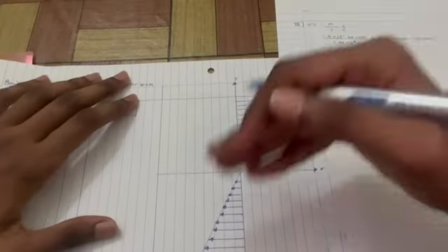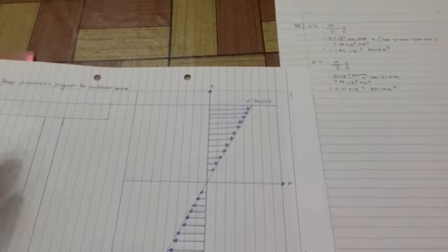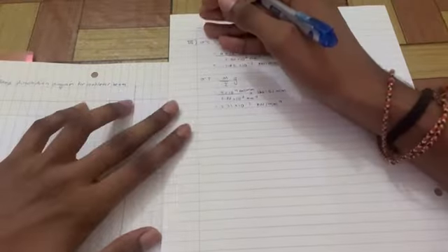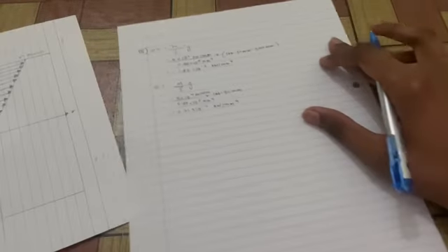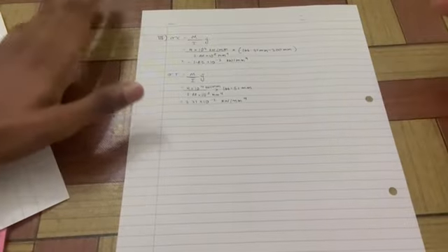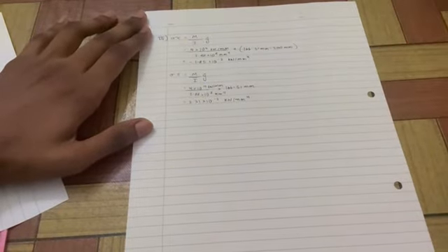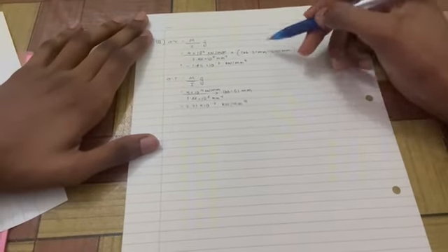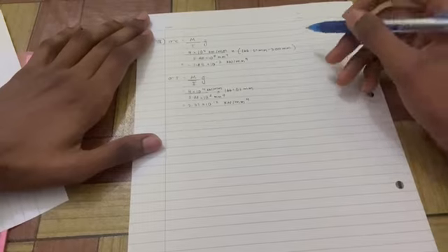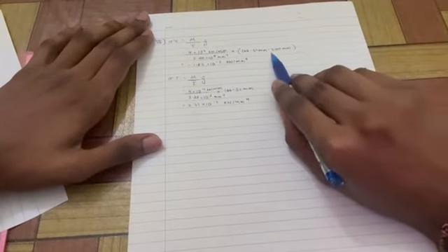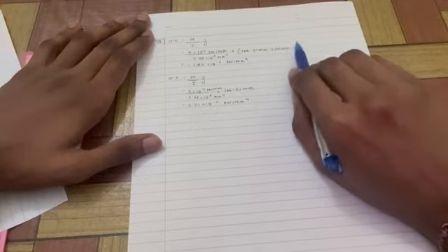Maybe most of you might be confused as to why I've drawn this tension and compression here, but the questions initially asked for maximum bending stress of compression and tension. And when it's about compression and tension, the formula that we'll use is M over I times Y, for both compression and tension. As you can see here, it might be the same, but there is a little difference. In this one there is this 300 mm.